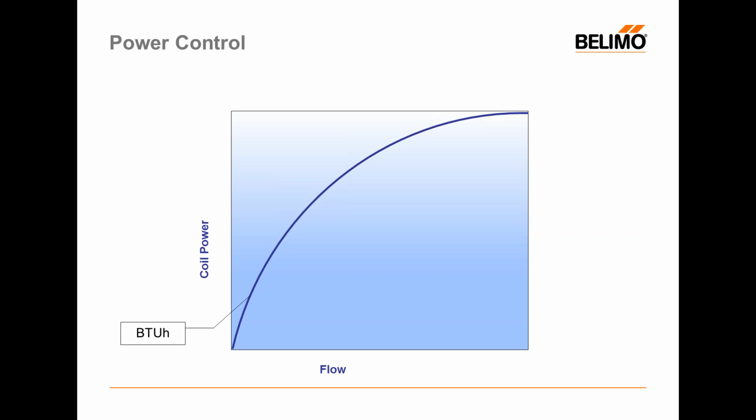Well, this is kind of a tricky shape to control with a controller. And so what the control valve typically does is try to have an opposite shape. So I'm going to draw a control valve curve on here as well. This type of curve is either called an equal percentage curve, or sometimes it's simply referred to as a characterized curve. And you'll see we have a different set of axes.